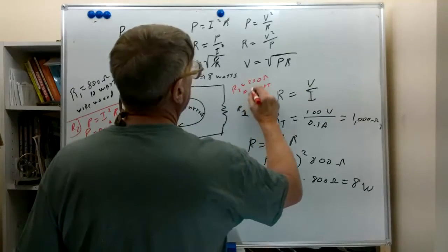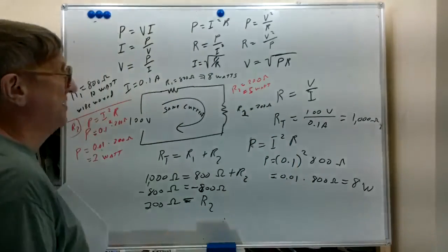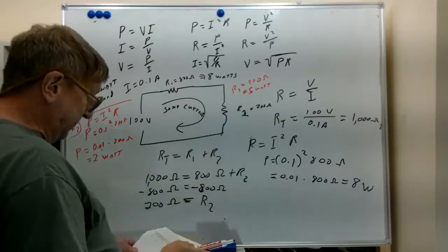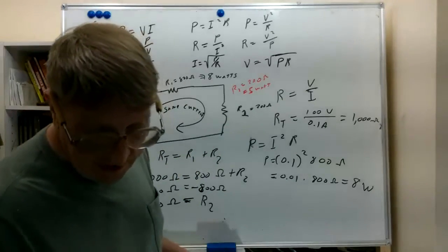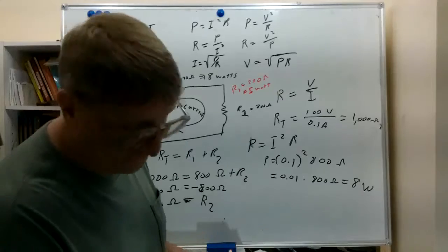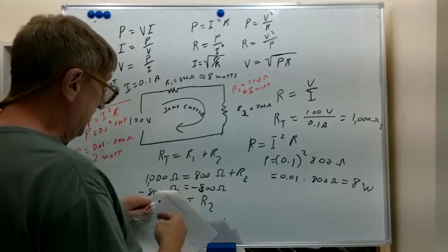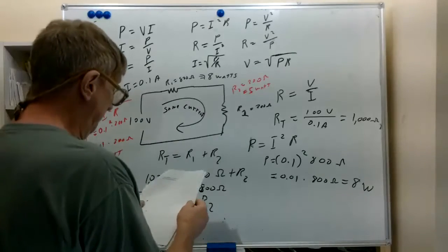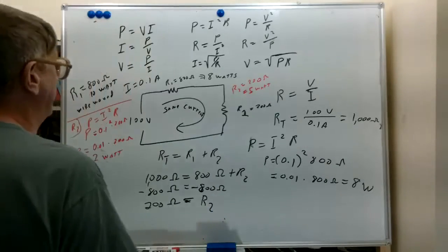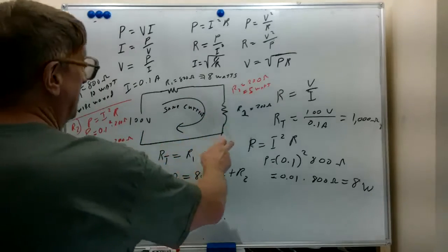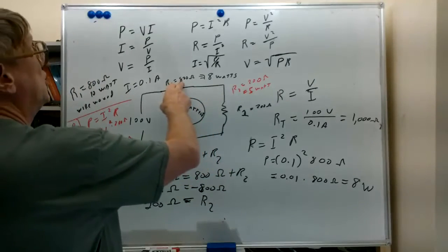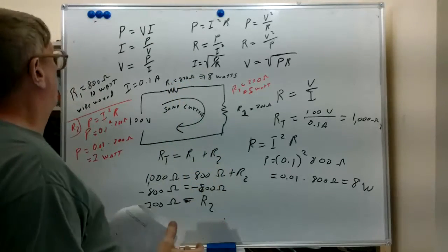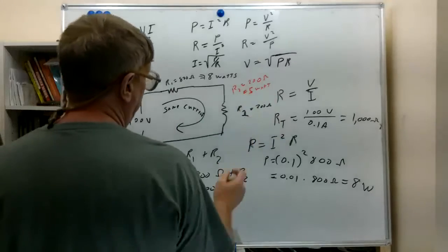So we would probably choose a 5 watt, which we can find in the carbon resistor, and that way we have plenty of power dissipation headroom. We're not going to have an issue with that resistor burning up in normal circumstances. And you can see also that with the same current through them, the larger resistance dissipated more heat and needed to be physically larger to keep from burning up than the smaller resistance needed to be.